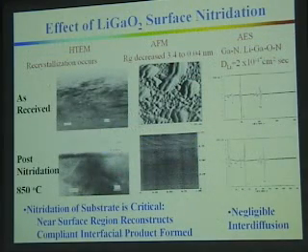Okay. First step was to take as received lithium gallate. This is a cross-sectional TEM micrograph, and this is the region here near the surface. You can see the near surface regime was not single crystal. It was amorphized. You will also see from this AFM micrograph that it was relatively rough, even polished. We had to learn how to polish it, but even so, it was still relatively rough, 3.5 or 3.4 nanometer roughness.